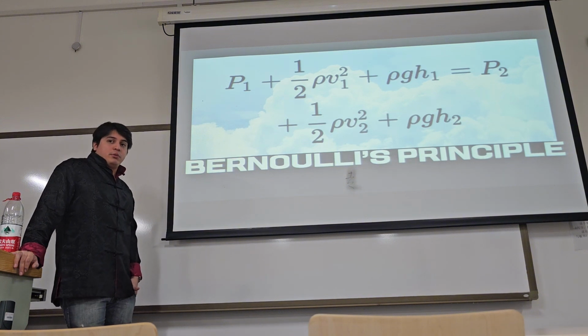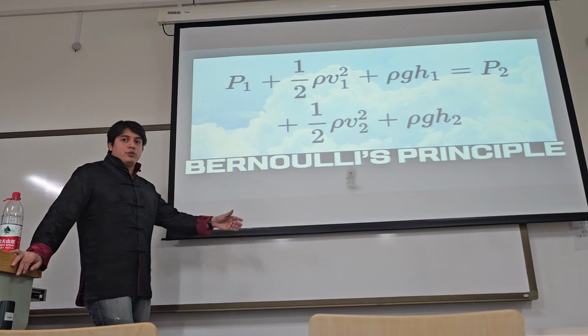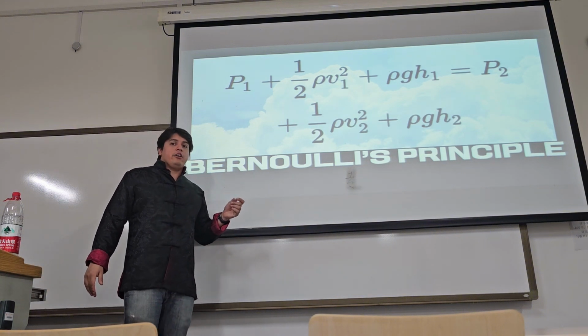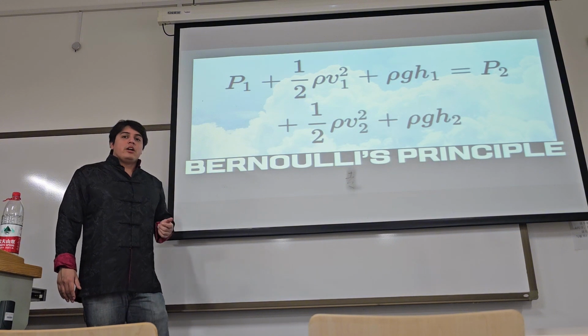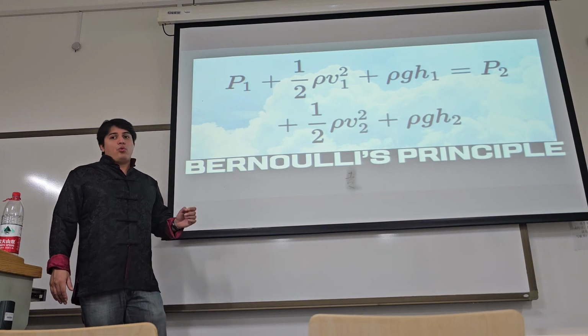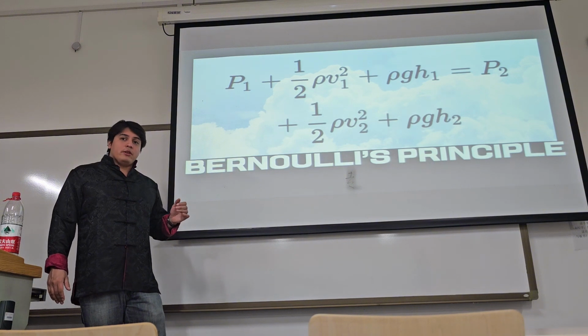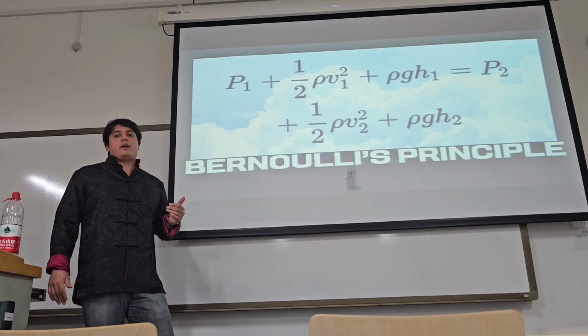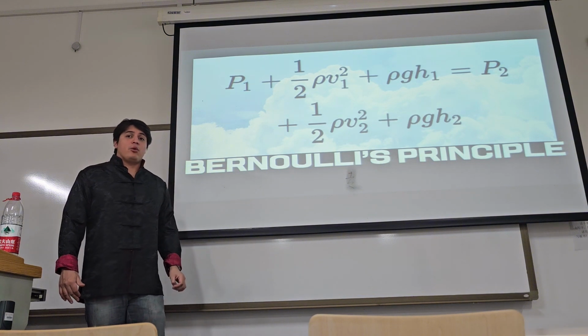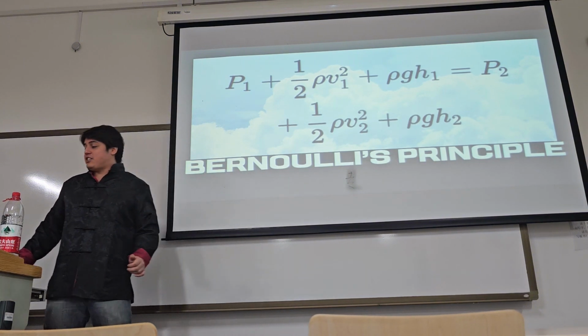According to Bernoulli's principle, if the air velocity over the top of the wing is higher than the air beneath the wing, then the pressure on the wing's top surface must be lower than the pressure on the bottom surface. This pressure difference creates an upward force on the wing known as lift.